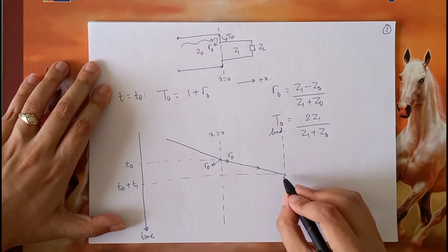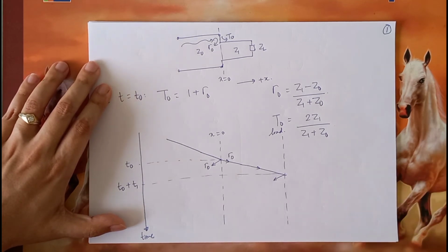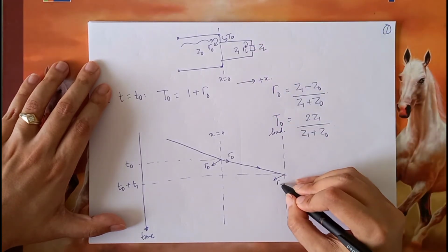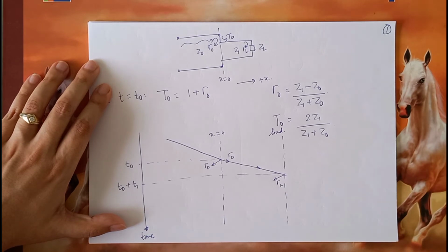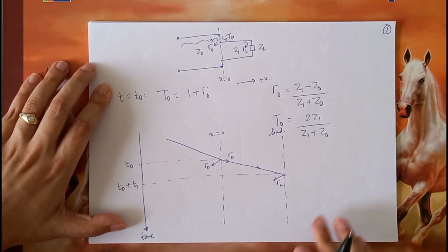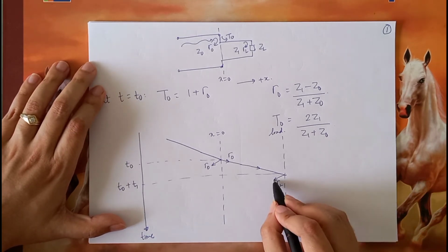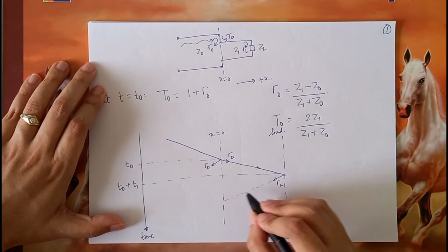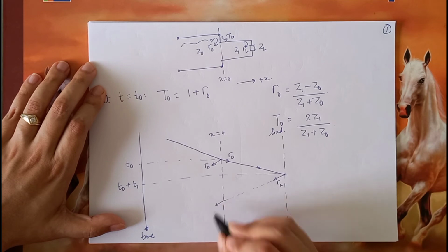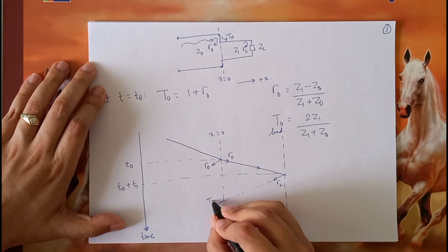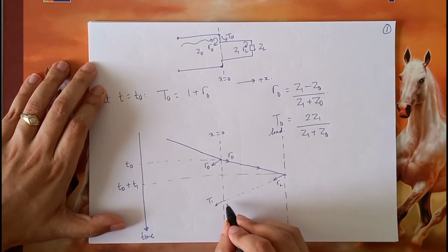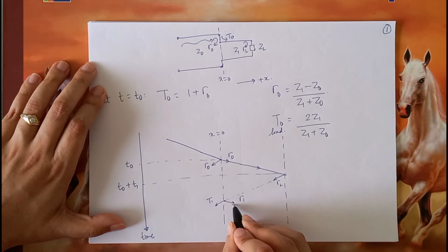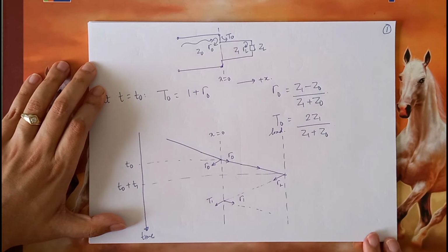So here, the reflection coefficient is the load reflection coefficient gamma L, and so on. So which then again comes back over here. Now it undergoes a transmission, let's call it T1, and another reflection coefficient gamma 1, and so on.